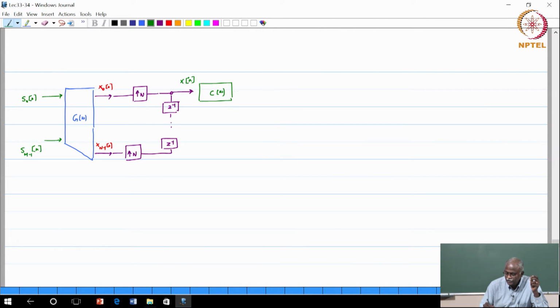There will be a noise term, but really in our analysis noise is not going to play a part. So, I am omitting that, but it is perfectly okay to introduce that. At the receiver you have these parallel channels downsampled by n. Notice it is an advance operator, z, downsampled by n, such branches, downsampled by n.